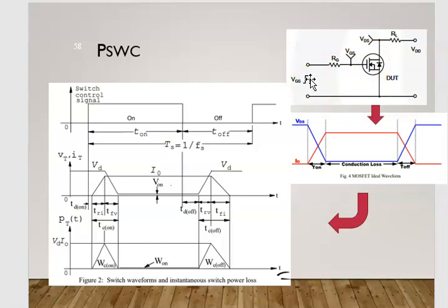For your simulation, you can set any simple gating signal, but for actual driving, you need to consider how much gating voltage this MOSFET needs. Minimum maybe around 10 volts, maximum maybe around 20 volts, and how much current needs to be driven or supplied to the gate. This is determined by RS, the series resistance of our gating signal circuit. Usually they put 1K, and here we put 20 volts.